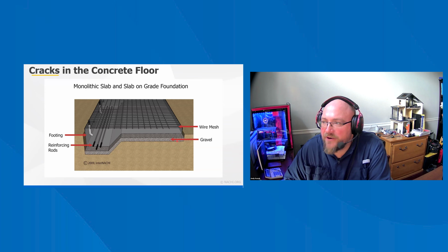The use of welded wire fabric reinforcement provides a means of controlling the severity of cracking. The use of fiber reinforced concrete may also provide adequate crack control. Concrete control joints may also be used to control random cracking by creating planned lines of weakness in the slab.